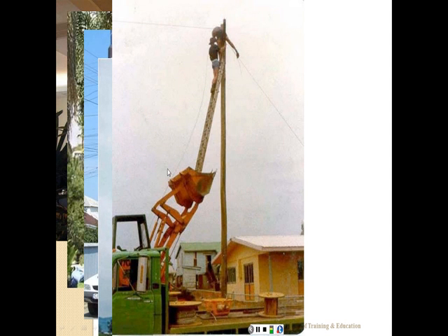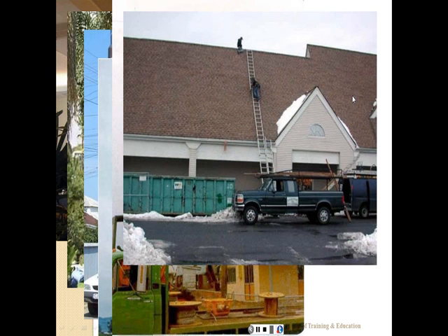Again, necessity is the mother of creativity. You should not do that at all. For several reasons. Working near a power line and then supporting the ladder on the bucket? Absolutely not. Several issues here. Not proper tie-off. Very tall ladder connecting more than 2 ladders together, and I don't think that slope even is 4 to 1. So there are probably 3 or 4 violations here.